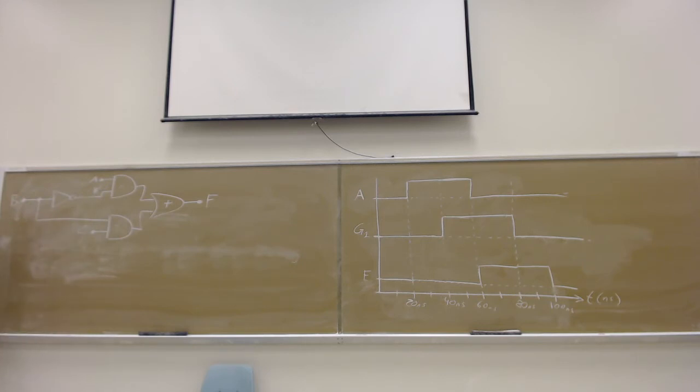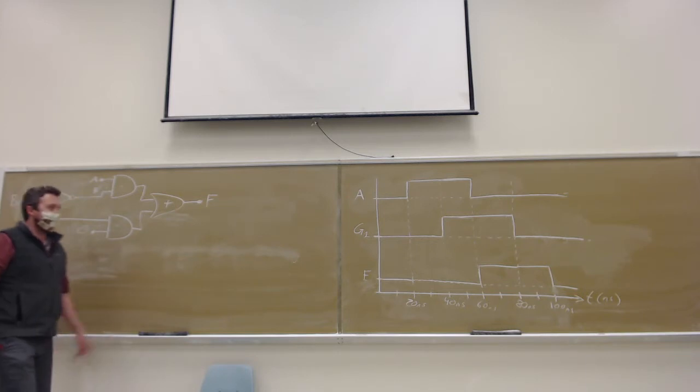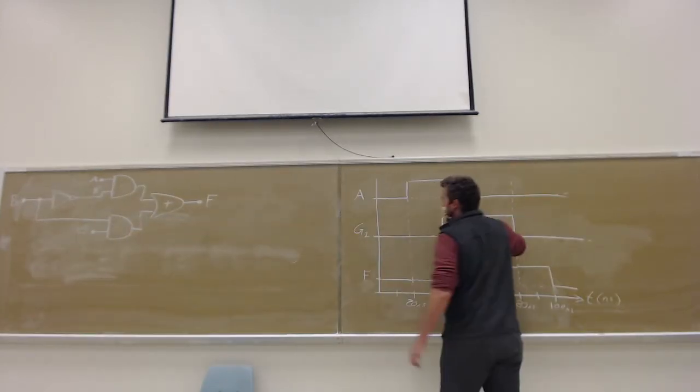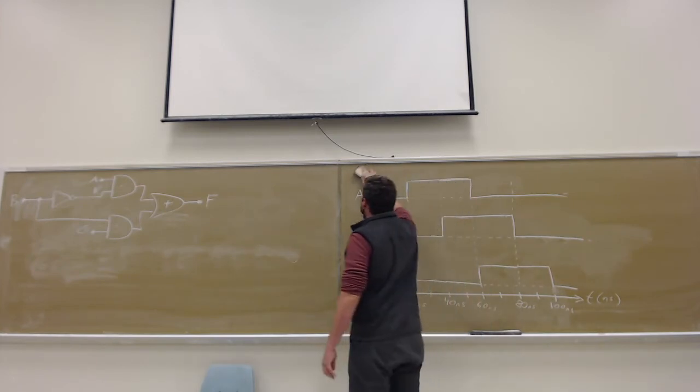So here's a question: how many levels is this circuit? 3? Gotcha. 2? 2, right? No. Why is it 2? Because you don't count the inverter. Yeah, except for now, when they do count, because we're talking about time. So this is still technically a 2-level AND-OR circuit.